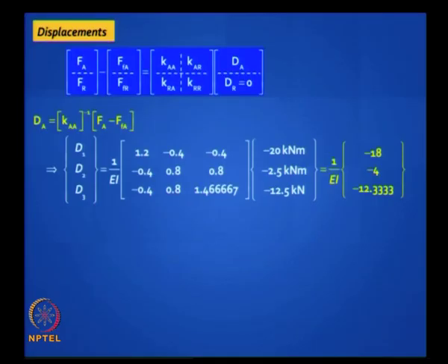So now these are your equilibrium equations. If you solve the first equation, you see how familiar this whole thing is now. Once you've got the method, you've got the solution. So solve the first one and you'll get some solution. In this problem EI was not mentioned. So if you plug in the value of EI, you will get the answer in millimeters and radians.